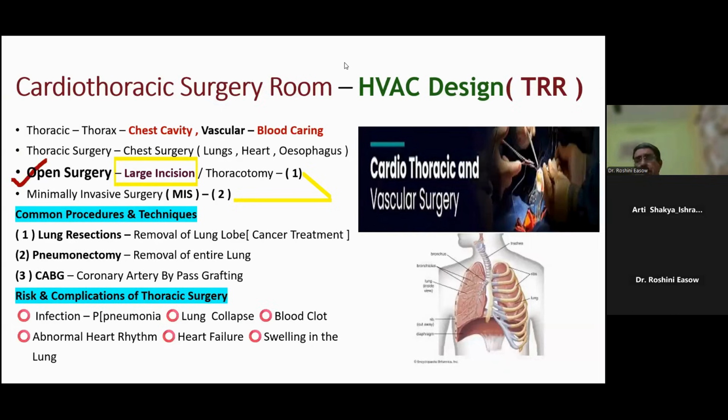Now, how to maintain a positive pressure? Say my design is 25 Pascal. I've explained that between the walls there is a K factor that a consultant has to consider in the design. What type of equipment and instruments are there? What will be the loss of pressure? Accordingly, the CFM has to be designed to maintain it. There's a total engineering calculation. How will I maintain 25 Pascal, because pressure depends on CFM? I showed you that calculation. But there is also a K factor, so it has to be considered to have an accurate design pressure.